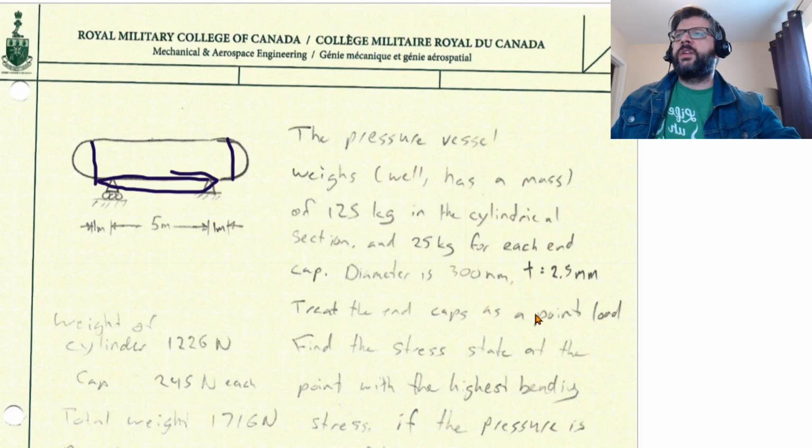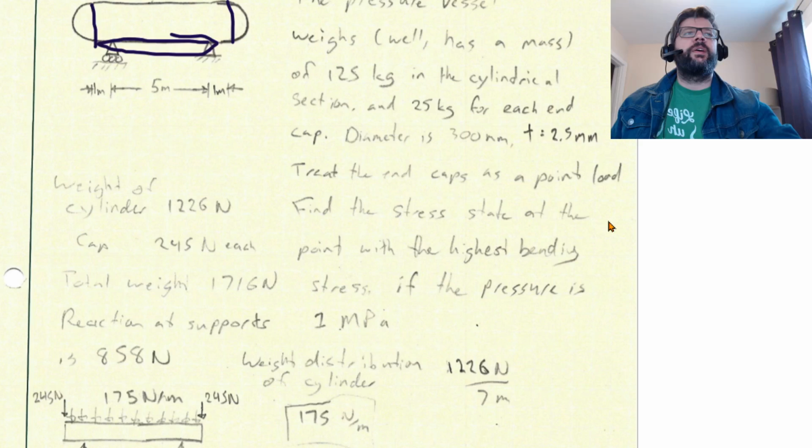So we're going to treat the end caps as point loads, basically, and then try to find the stress state at the point with the highest bending stress if the pressure is 1 megapascal inside the pressure vessel.